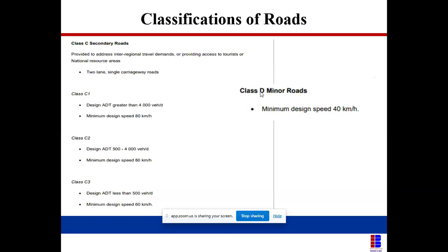You see the effects of the design speed. If you put a particular design speed, and you've customized that to be 60 kilometers per hour, and you go below the radius, it gives you a flag sign showing that there's something wrong here. That is just the radius, the K values, and all is below the design speed specified. So once we go into the software, we see the effect of design speed on all roads.